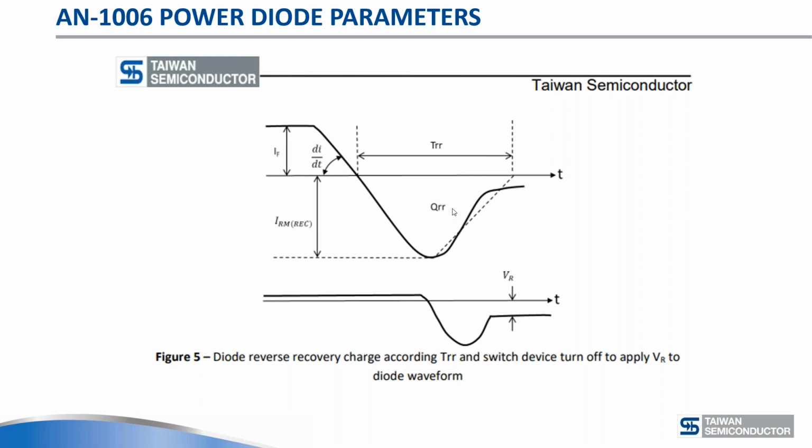What you also see here is the voltage over the diode, where the diode actually starts blocking at this stage. What you need to understand is that because of the reverse recovery time and the losses, there is not only a loss in the diode, but also a loss in the switching element, so both absorb a loss because of this QRR.